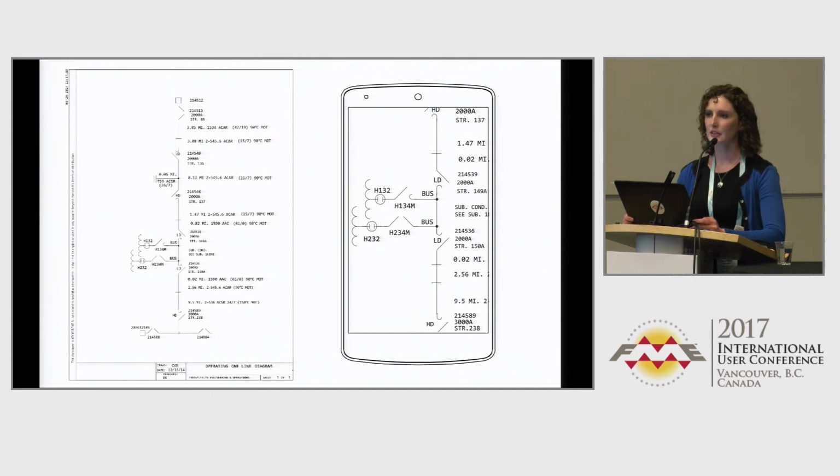Yeah, I did try several different things. I ended up using the rich text, so I turned it into an XML string. I did try turning it into a line string, and I tried rasterizing them so that it read the font as an image. But for some reason, when it did that, it was creating weird boxes on every corner of every letter. I don't know if it was a setting or if it was due to the MicroStation font in the first place.